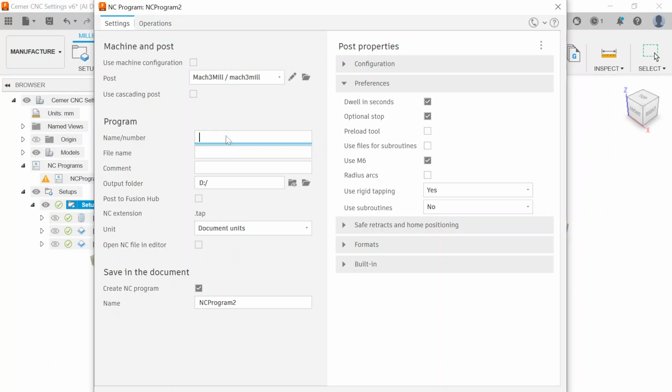And I also like to copy and paste that down here as well. If you wanted to call it bracket or whatever, you need to give it a distinctive name instead of random unnamed stuff. And then you click your post button and you will have a .tap file that is good to go. Whatever you design, I hope you enjoy the heck out of it.